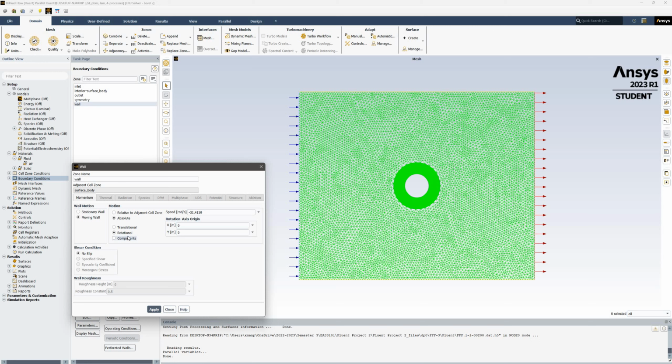And so that means when it's flowing over the top of the cylinder, if the cylinder was able to just freely rotate, that flow would be making it spin clockwise. So to make the streamlines look how they are in the project requirements, the cylinder needs to spin clockwise. The negative is because Fluent treats negative as clockwise and positive as counterclockwise. So the cylinder is spinning clockwise at 31.4159 radians per second.